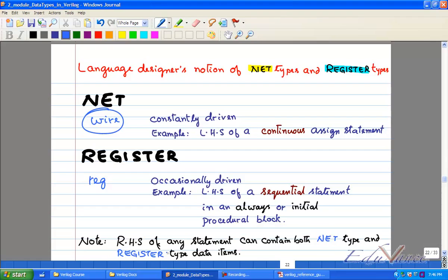But if one point is 0 volts and another which I want to choose as reference is 4, and if I choose less than 2.3, then current will flow from one point to another. One second. Can you repeat your question, please? Once again. If my reference is 4, above which is considered as 1 and below which is 0. That is not defined by that. That is defined by the transistor on the other side. There is a transistor sitting there. The threshold voltage of the MOS transistor defines your 1 and 0.